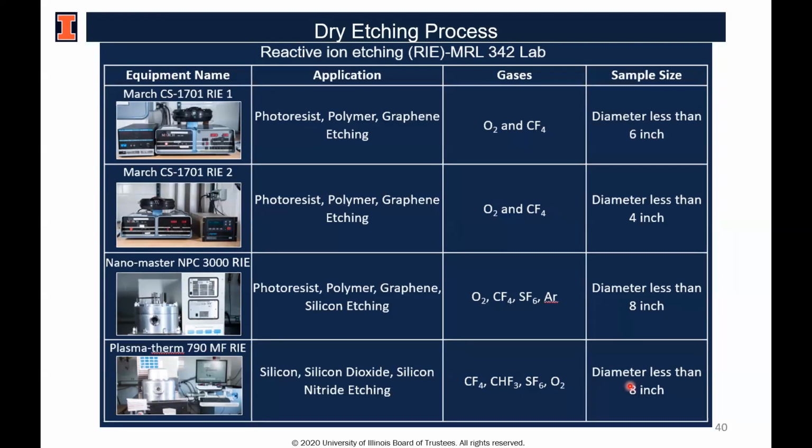However, wet etching is normally easy to accommodate, but dry etching is a little bit hard, and it's easy to control, but it's hard in terms of money, because you need to buy the instrument, right? Also, wet etching is less clean, less environmentally friendly, and the dry etching is actually much cleaner and more environmentally friendly.